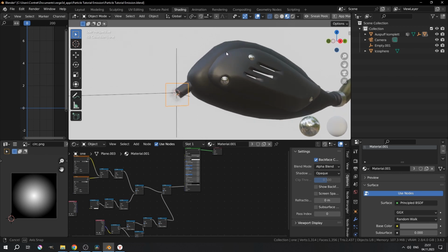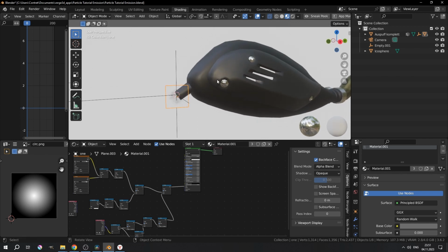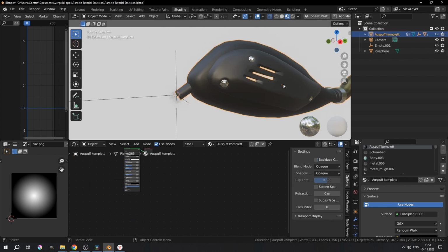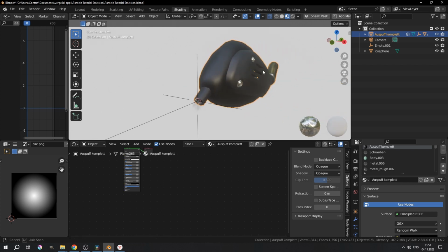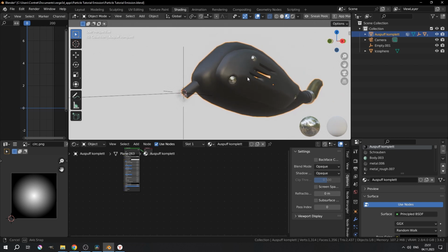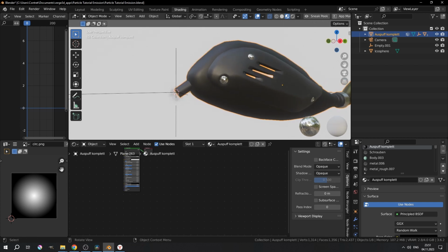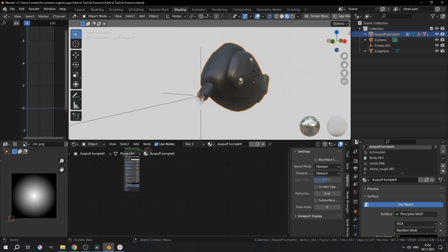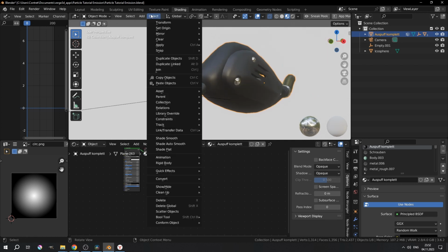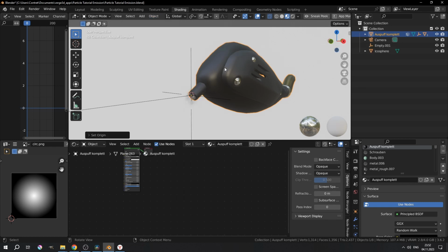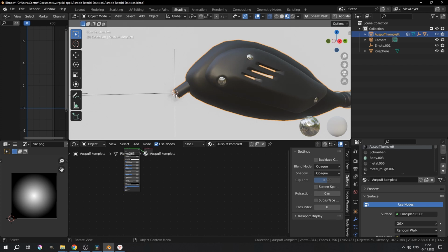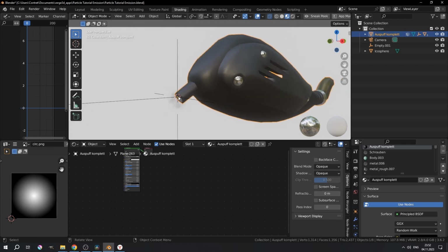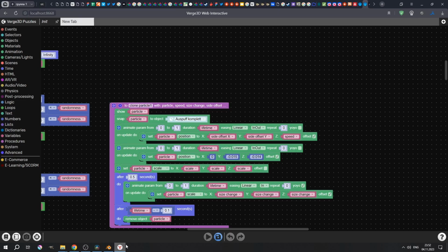First we need to set the point where the particles will snap to and move from. That will be the origin of the silencer. Right now the origin is in geometrical center. Well, in most cases it is. We need to move it to where the particles will come from. To do that, I have already placed the 3D cursor here, and now we just need to select it and go to Object, Set Origin, Origin to 3D Cursor. Now the origin jumped to the end of the exhaust pipe. It may not work the best with animation, so we can parent it to empty or another object.